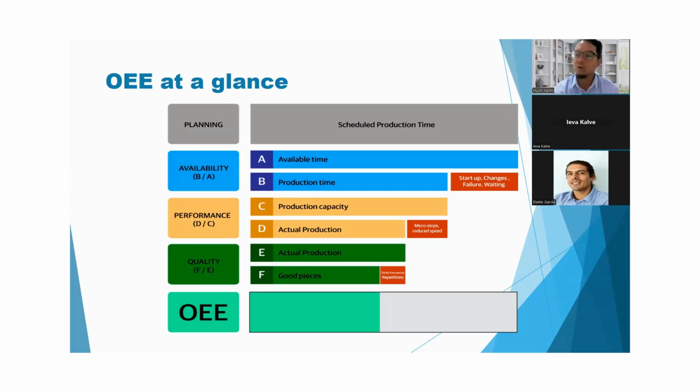So in a way, OEE is a way to make it visible, so that all the wastages here are transparent to everybody. So let's say if you have the OEE for, let's say, 50%, you are seeing that 50% of your production time is a waste. So from there you can see there's a lot of wastage that you can improve.